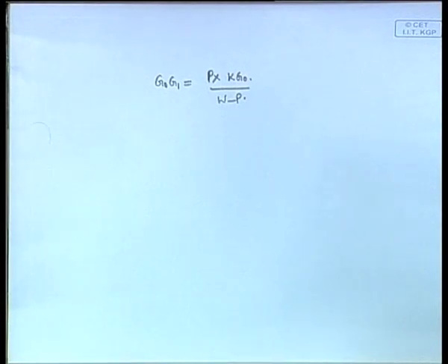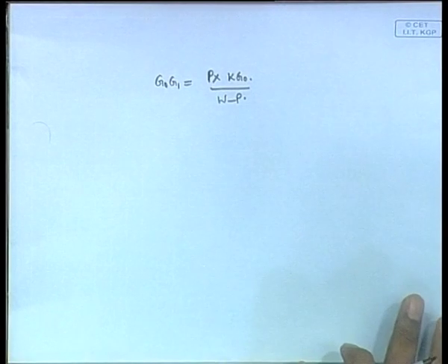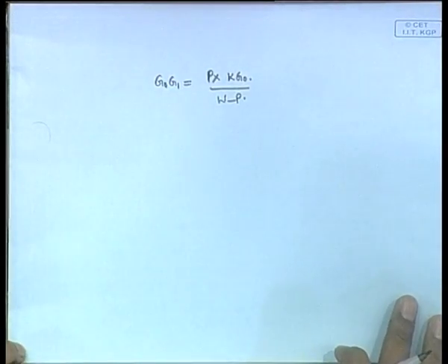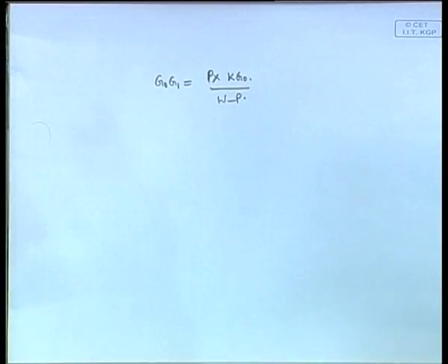As you can see looking at the problem, aft is below, therefore it is going to dry dock like this. At the critical instant when it touches here, P will come here, acting here. So, P into L by MCTC will give you your trim. It is not an assumption, the ship will go like this only.